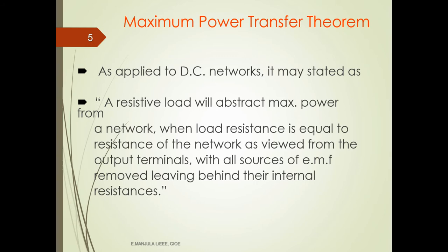So here, what this statement is saying is that the load resistance will absorb the maximum power when the network resistance, the total resistance in the network as observed from the output terminals, is equal to the load resistance, provided all the sources of EMF in the network are replaced with their internal resistance.